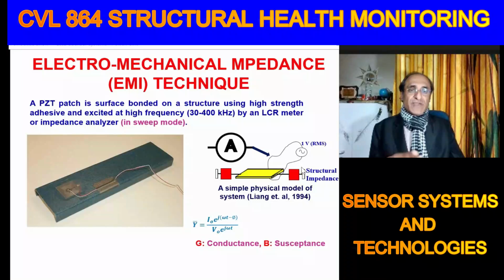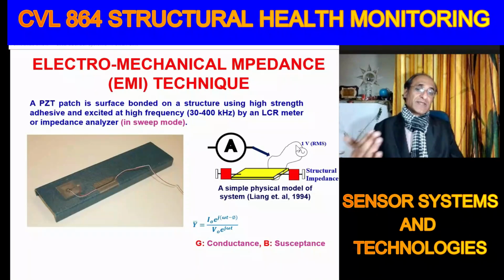And because there is a phase difference, see, always in dynamic phenomena, there will be a phase difference. Even in the LCR circuit, that is the main point we study in LCR circuits: there is always a phase difference, L, C and R. In one component, the resistance, the current and the voltage are in phase. In the case of inductance, the voltage leads the current by 90 degrees, and in the case of capacitance, the voltage lags behind current by 90 degrees, right?